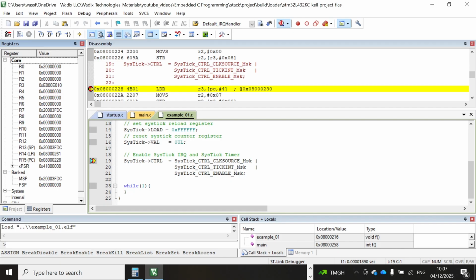So once we get the interrupt, we will see that the stack pointer will be decremented by the number of CPU registers that have been saved times the size of each of those registers. In our case, all registers in Cortex-M are 32 bits or 4 bytes.